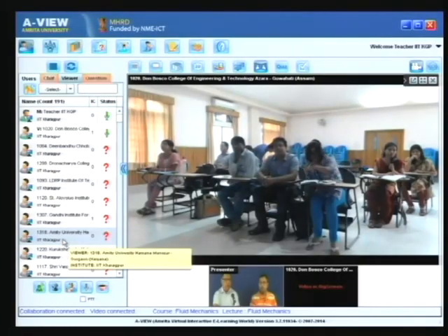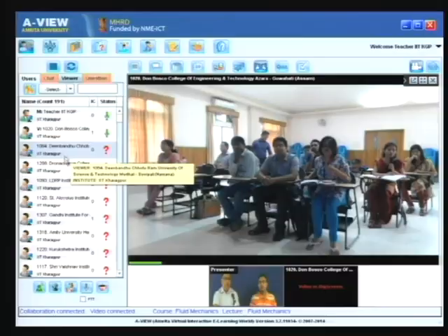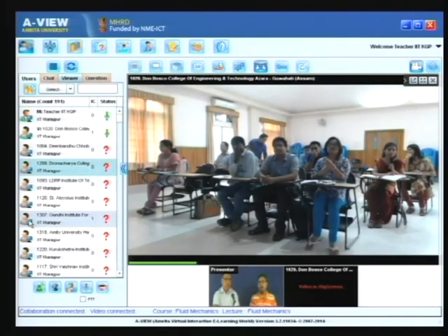So if that is the question, you have to refer to not the Bernoulli's equation but the mechanical energy conservation equation. So you have to calculate the sum total of P by rho g plus V square by 2g plus z at the 2 points 1 and 2. So the fluid will flow always from higher head to lower head.